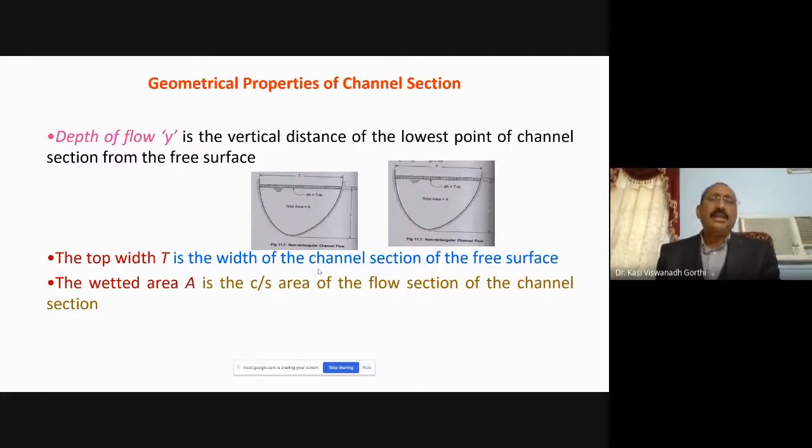Now, we see some of the geometrical properties of the channel sections. We have been using terms like hydraulic radius and hydraulic depth and so on. Let us see what these geometrical properties are. Depth of flow. What do you mean by depth of flow? In a canal, for any of the shapes, the depth of flow is from the free surface to the bottommost point. You see in the figure, this is the free surface. So from the free surface to the bottommost point of the channel is called the depth of flow.